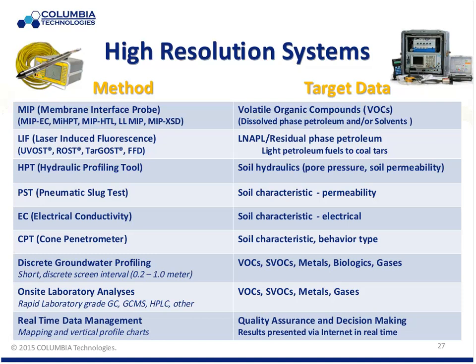The second item on this list is the family of laser-induced fluorescence tools. For the world of NAPLs and LNAPLs, this is an ideal tool for determining source area footprints and configurations. It uses a principle of high-energy lasers working in the ultraviolet spectrum, about 308 nanometers, shoots a light out down a fiber optic out a sapphire window, and if there's a wayward petroleum molecule outside that window, it'll excite and fluoresce with a unique signature of its PAH structure, and we'll pick that signal back up a second fiber optic and take it up to the surface and do signal processing of that.